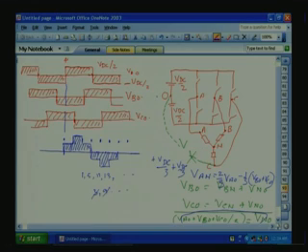Okay. This is the A phase waveform. Now, B phase waveform will be 120 degree phase shift. Okay. That we can draw. Once you get the thing, other thing we can easily get. This is 1/3, 1 by 3 VDC. This will be 2 by 3 VDC, this height.